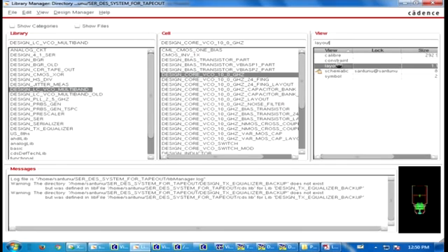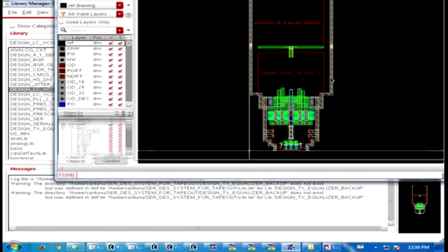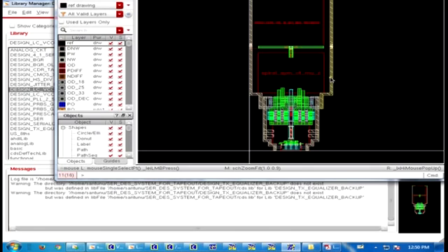Now see the layout. The most difficult part is to design a VCO at high frequency. It will work in schematic even with 3.5 milliampere or 4 milliampere, but in layout you cannot get the result with that current. So you have to think very innovatively how to make the layout of the VCO, then it will work after post layout.